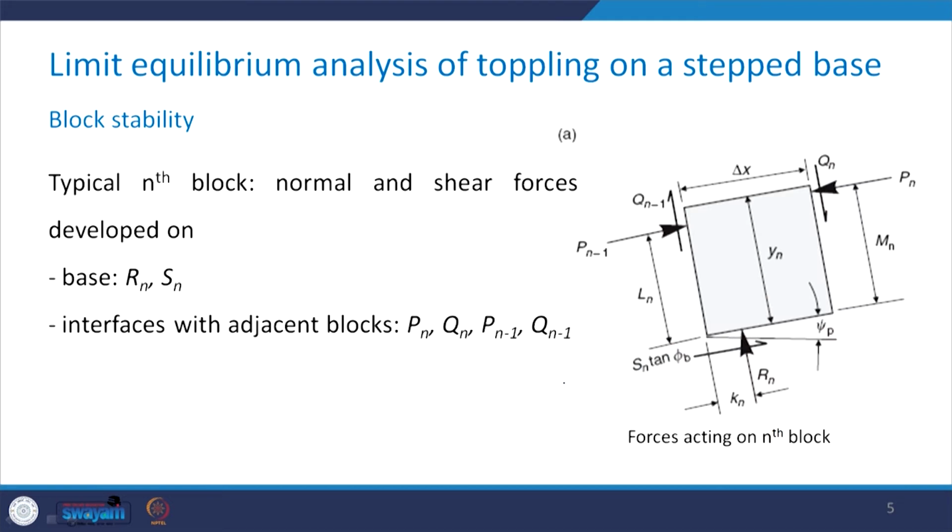Now let us consider a typical nth block. The normal and the shear forces that are developed on the base, I mentioned to you, are Rn and Sn. At the interfaces with the adjacent blocks, as shown here, the normal forces are Pn and Pn minus 1, and the shear forces are Qn and Qn minus 1.